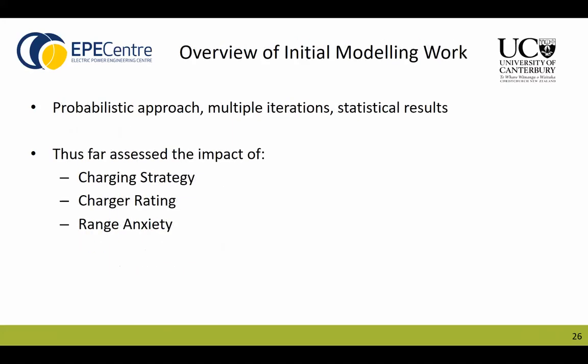A probabilistic approach is implemented, which performs multiple iterations of the week-long load flow simulation and therefore produces statistical results. Work so far has assessed the impact of charging strategy, charger rating, and range anxiety.